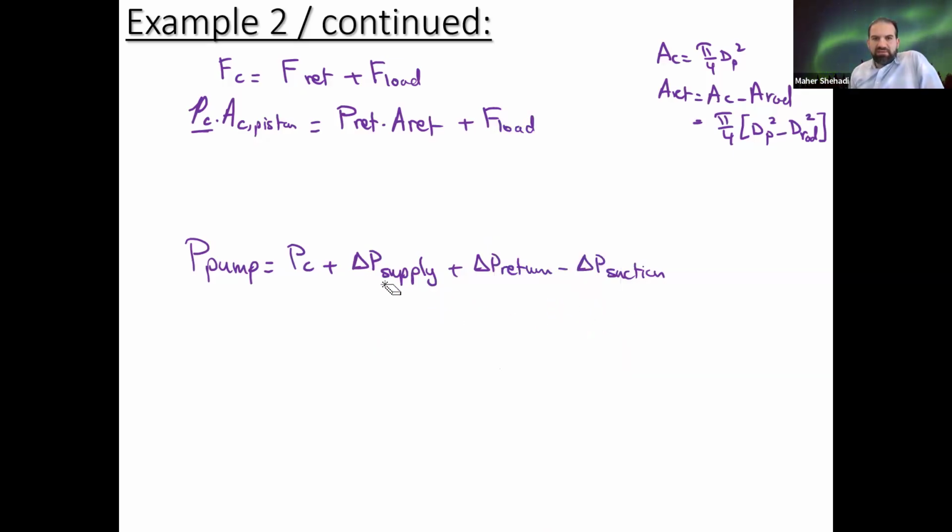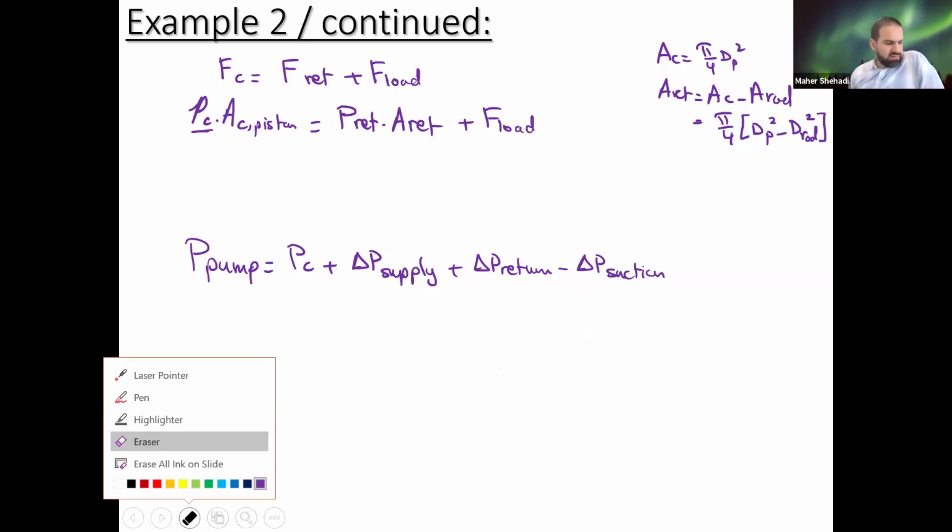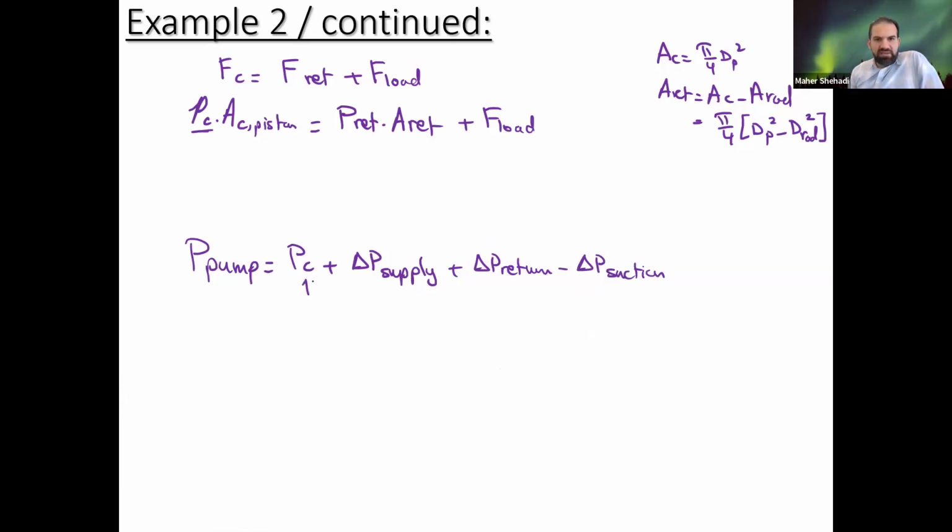So we have this is 75. We have the return, it's 50. And this one is minus 4. So we can have that. So my missing variable is on the cap side, and that's why we needed to do that balance there, because I can't add a pressure created by the load to be able to push it, or friction between piston and cylinder. Where these would happen, it's actually inside this equation.